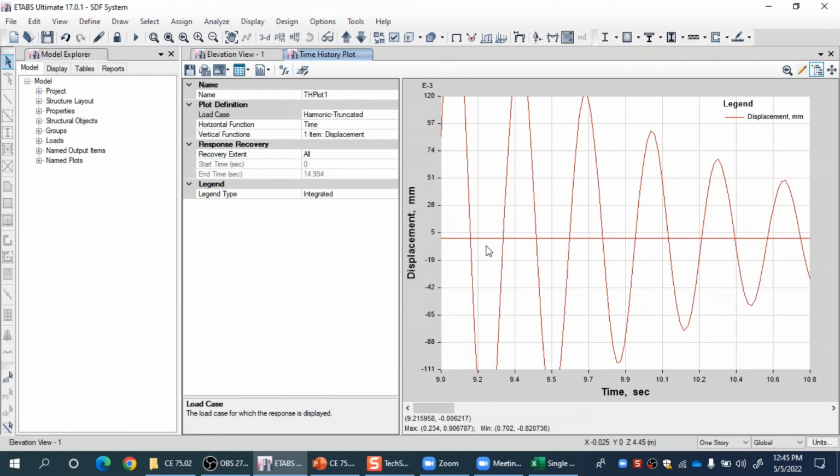If the time history was 15 seconds, the value will be calculated for all 15 seconds. Then you can make a practical design decision after looking at the complete time history of response, whether you have to pick the peak number or the root mean square of a few peaks, etc.